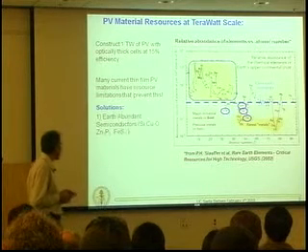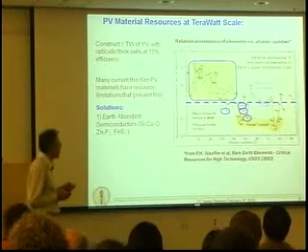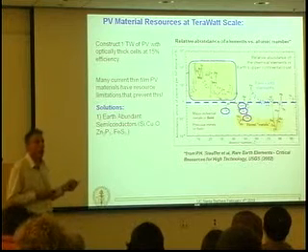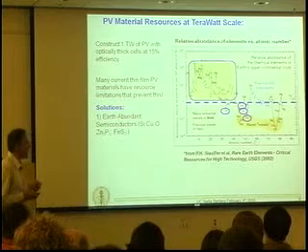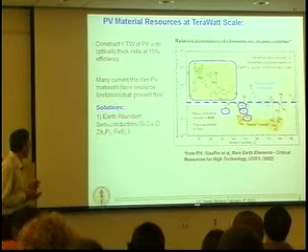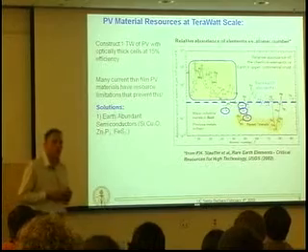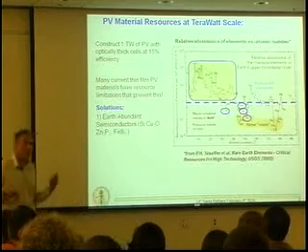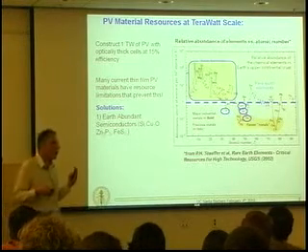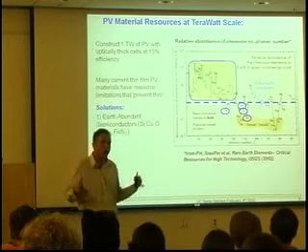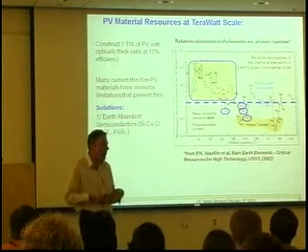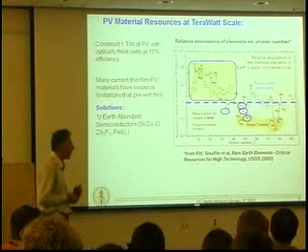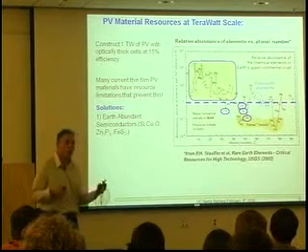So one way we might innovate our way out of this conundrum would be to make photovoltaic materials that are essentially mineral-like semiconductors. You might imagine looking at compounds like copper oxide, zinc phosphide, iron disulfide, iron oxide, things like rocks and rust and things that you find in the desert. But of course, we don't normally think about these as electronic materials, and the reason we don't is because years and decades of investment haven't been made in the purification and crystal growth of these materials, many of which exist as useful semiconductors. We don't know a lot about their doping properties.